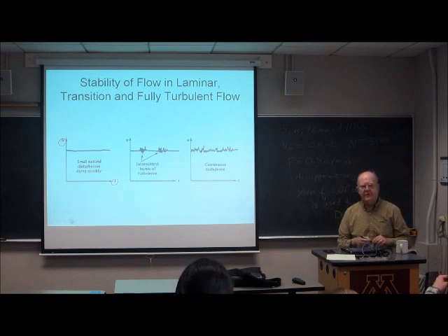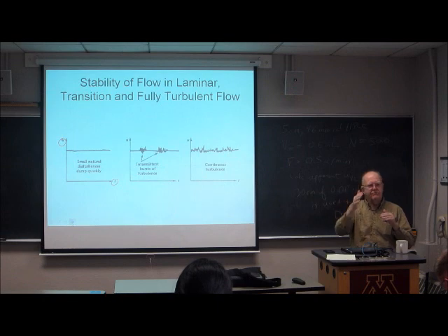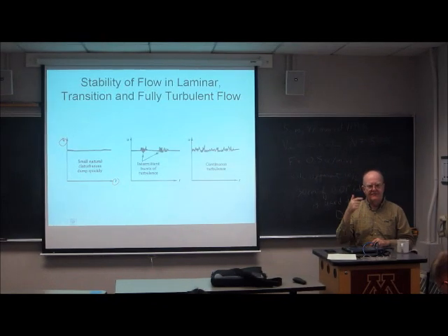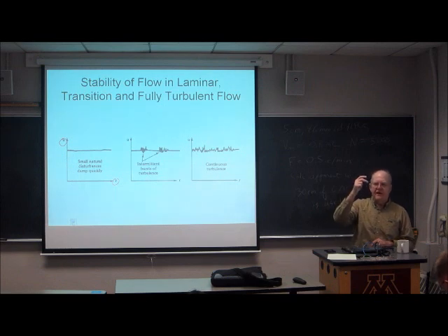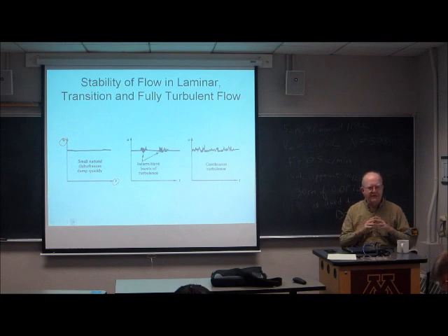So there are three consequences of going into turbulent flow. Number one, the parabolic profile flattens out. Number two, it costs you more pressure to increase the velocity than under laminar conditions. And number three, the velocity at any given point in the system is no longer quiescent. It's no longer time independent. It's very randomly time dependent.